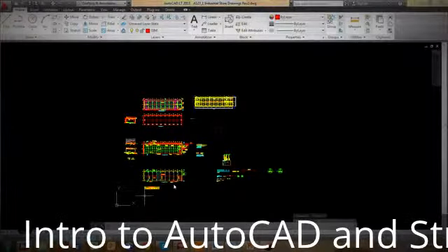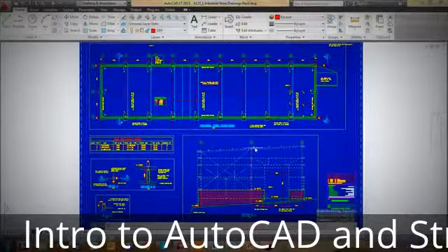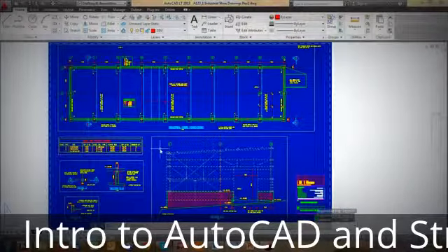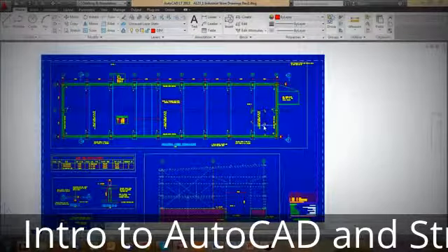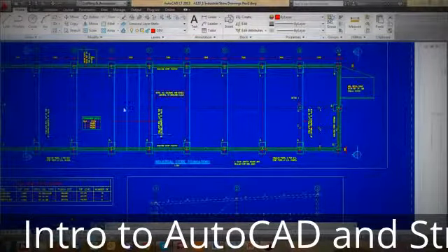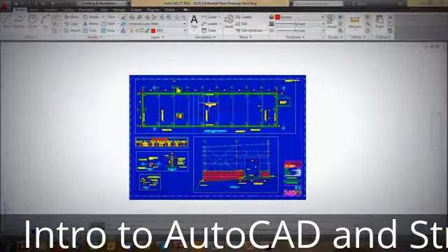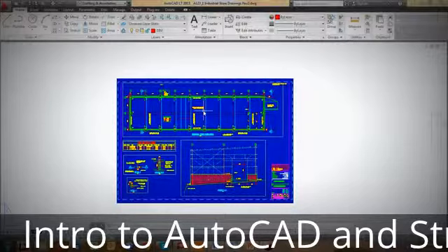So from model, you set up a window around it. So I will see what's in that box right now. But you create those windows from paper space. So if you go into paper space, you look now through these windows. And what you must be careful of is even though you draw at 1 to 1 in model space, all your dimensions, your styles, etc. must match the scale you use in paper space.